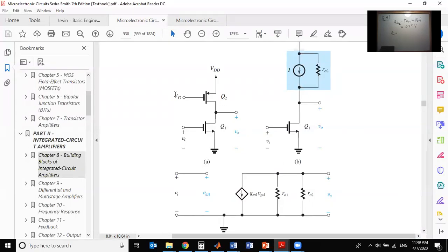Can you just subtract VDD? That's correct, yeah. It's VDD and subtract VSG, right? Because VDD is connected to VS, right? Yeah. VDD is the same as VS. So if you subtract VSG, you will be at G, right? And because you don't have any resistor there, there's no drop on the resistor. Just from VDD to VG, you just subtract VSG, okay?